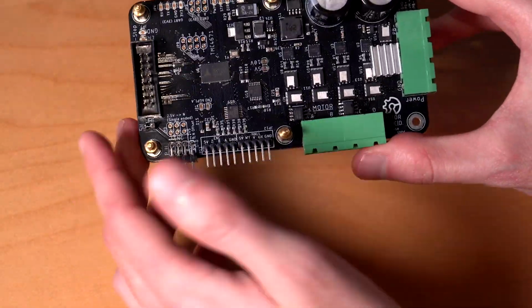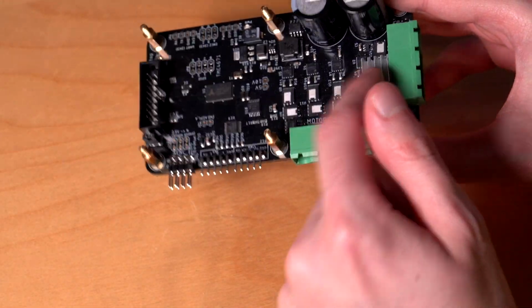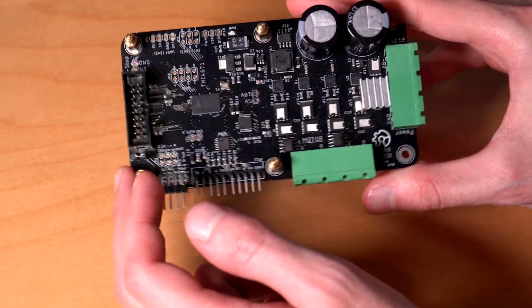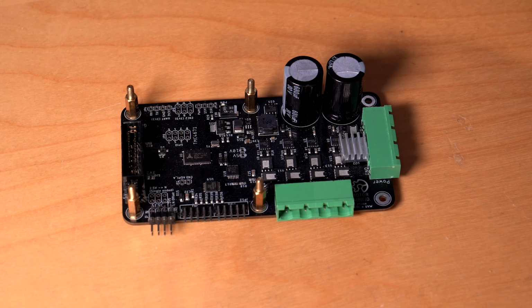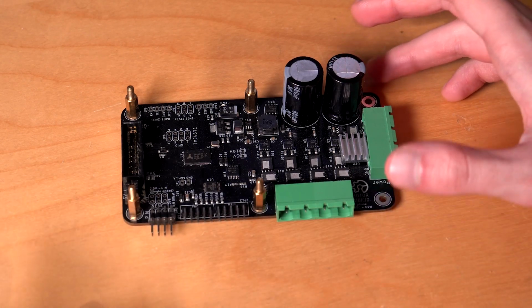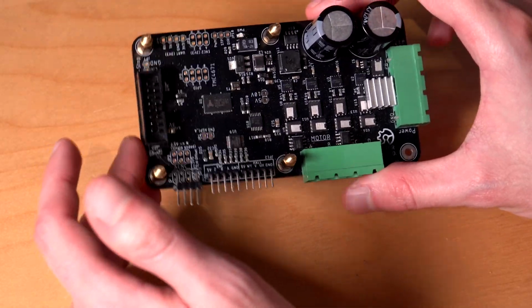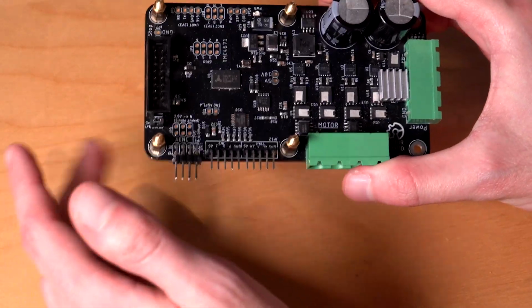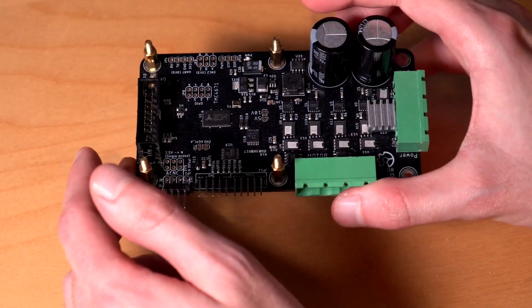And I mean, the diode is also less efficient than a MOSFET, so I added a heatsink on this board as well. I wouldn't recommend using a diode instead of the LM74700, but because of this availability issue of so many parts, I have not released the files for this version yet, and even if I do, please keep in mind that you may not be able to buy some of the parts, or that they were already replaced by me, and you may need to find some alternatives yourself.